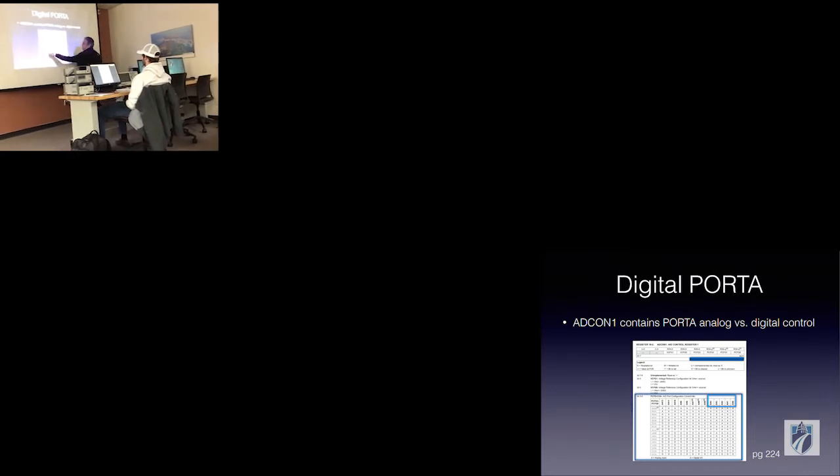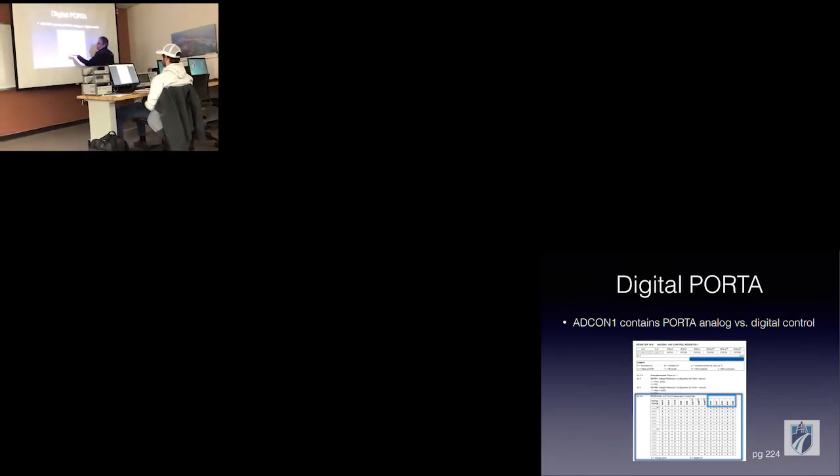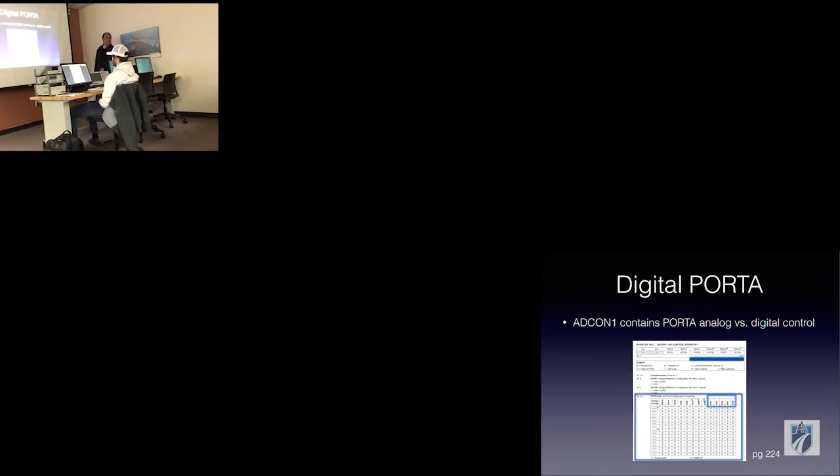So this is the software value that will make this circuit behave that way. So if I want to make AN4 digital, right here, 4 is digital, but the rest are analog, you have to put there hexadecimal B. See that? You just have to read the table. Just read the table.